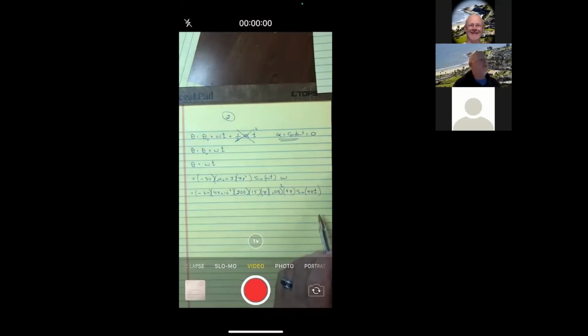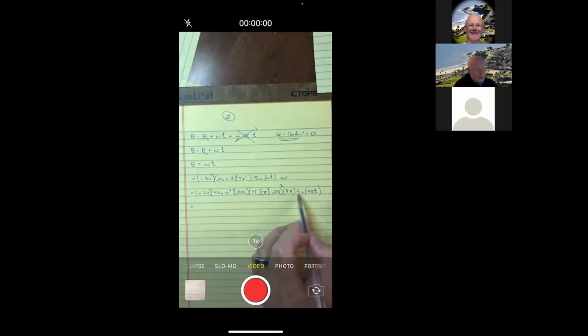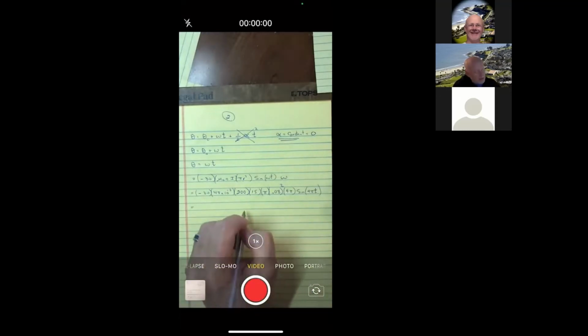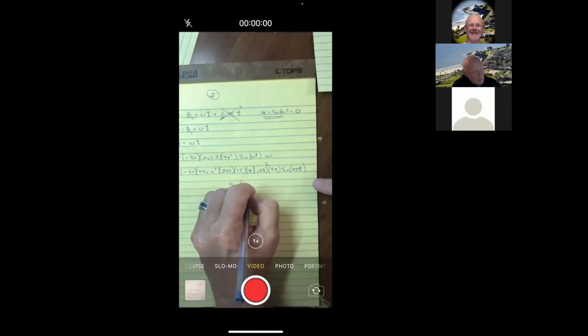So here's a function of time. When they say determine the EMF as a function of time, what they're saying is put in everything you know, but of course you can't put in a value for time. I didn't give you a specific time. So you should have everything except for time in there. This will ultimately be some number out in front, and then sine 4 pi t.